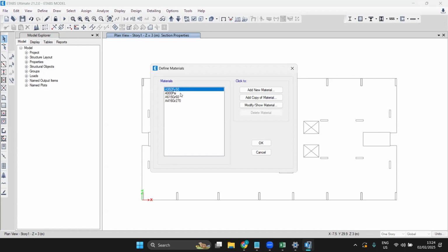And we did not introduce any beams. Make sure there is no beam here. It's only a flat slab. I'm not going to introduce even the peripheral beams. Let it be completely flat, a complete flat plate with shear wall only. If it fails under punching, let's see. Deflection, I will tell you how to control. There are several ways to control the deflection.